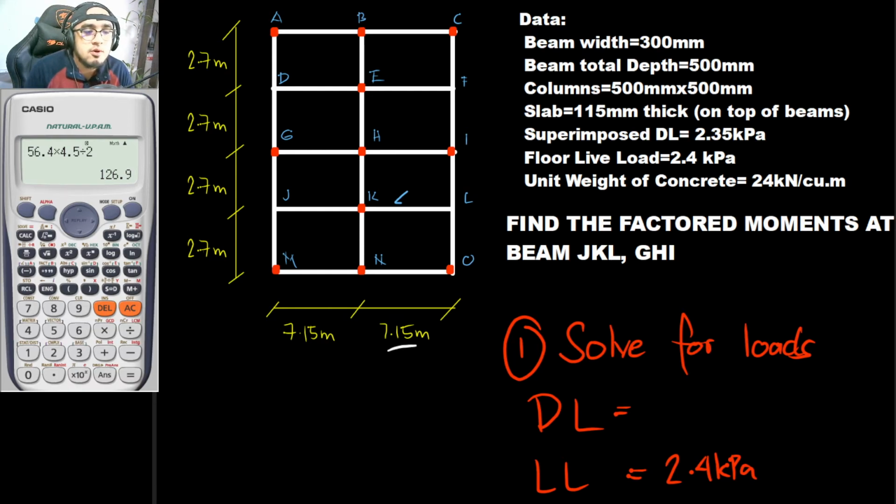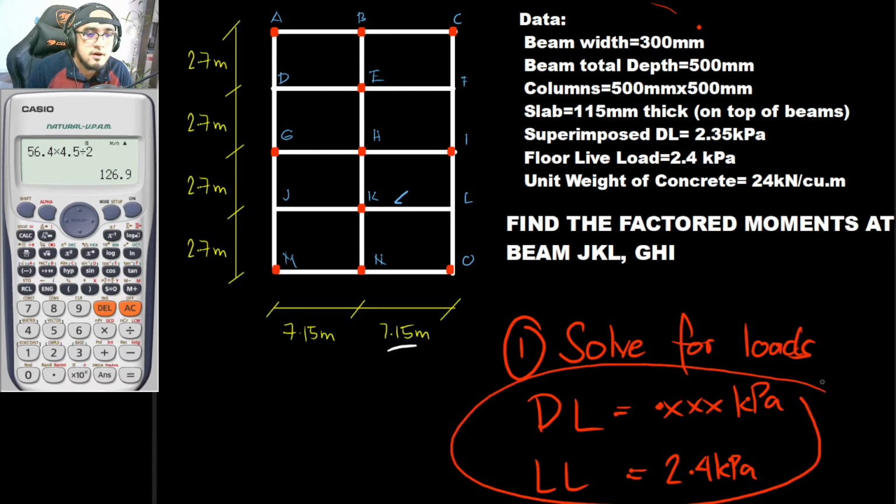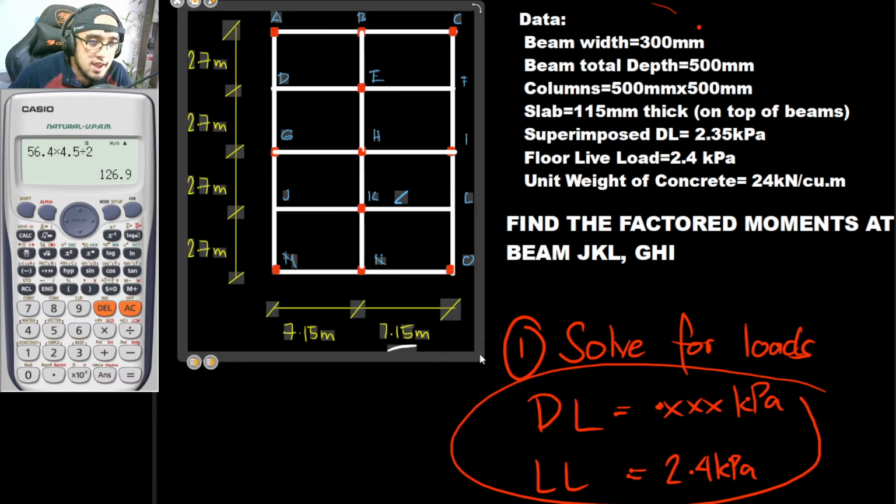So for example, if you are solving for the weight of the beam, then you will just be multiplying the area here, I mean the volume or the area, by the unit weight. So ang kalalabasan dito is to be in terms of kilopascal. Kunwari may masolve kang a value diyan. But the thing is, di ba sa approximate method natin, they are to be in terms of kilonewtons per meter. So now, how can we convert this pressure into line load?